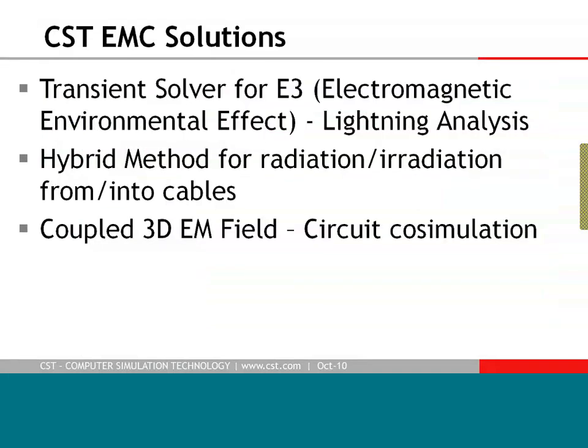How can we solve this kind of problem? First of all, we need a transient solver, since general electromagnetic environmental effects are all in the time domain, like the lightning analysis. We have seen the presence of plenty of cables inside, and I will introduce a hybrid method that CST software uses in order to simulate a 3D environment with very detailed cables.